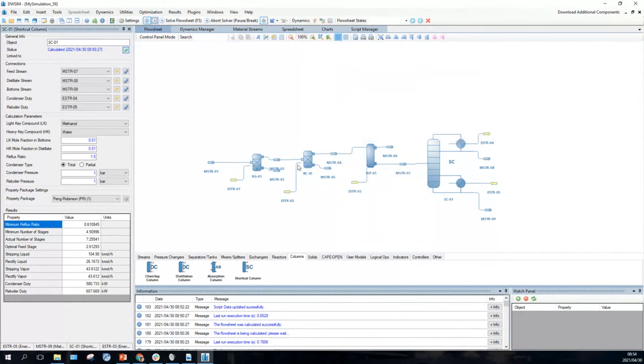So you'll have to just check your reactor, your conversion reactor. Obviously, if it's blue, you must have got the mass balance right, the stoichiometry right. Yeah, and it's 90% conversion. What did you select for the phase in that reactor? Yes, the phase must be vapor because this is 250 degrees C. Okay, I also have vapor. All right, well, let's carry on.